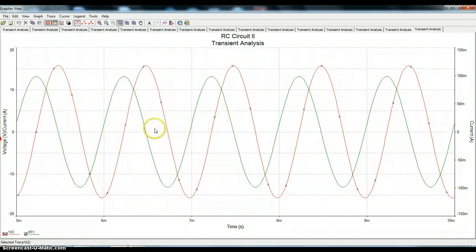So if I wanted to, I could measure things like the phase shift between the voltage and current for steady state AC. If I wanted to do that, I would recommend going back and plotting it over a much shorter time interval so that the scale stretches out. So, for example, we could measure it even over 1/2 cycle, and using that time basis, we can measure what the time here is and represent that as a fraction of the time for one cycle and get the amount of phase shift. But I think the point has been proven in this case. So by using the process of steps that I showed, you can actually activate the right scale.